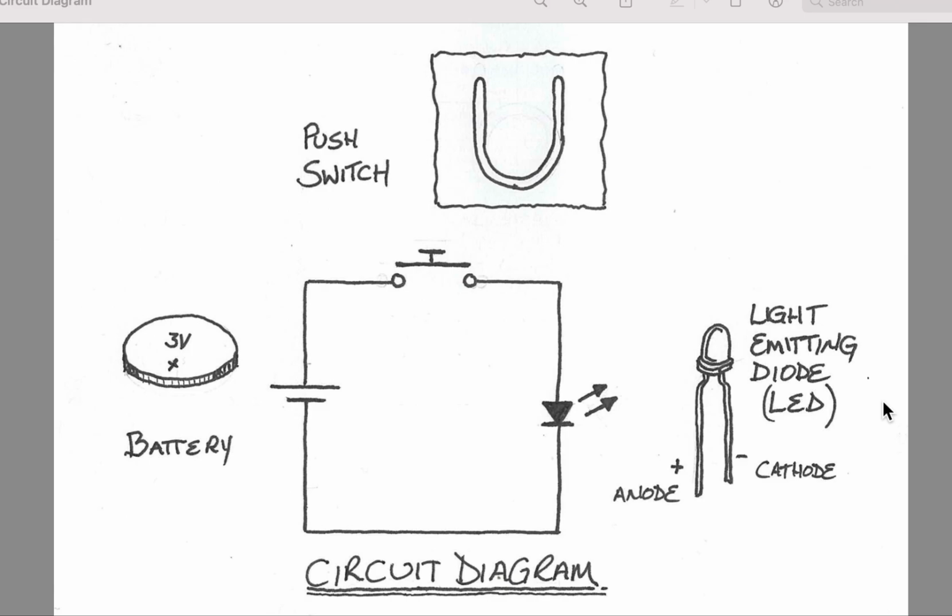They're available in different shapes. So when we look down on the top, most of them are round, but we can get them in squares and also triangular as well. The most common size is 5mm diameter, but you can get 3 going down to 1.2 and actually going up to about 12mm as well. The colours tend to be red, although you can get them in blue, green, amber and orange as well. But like I said, red is the most common.